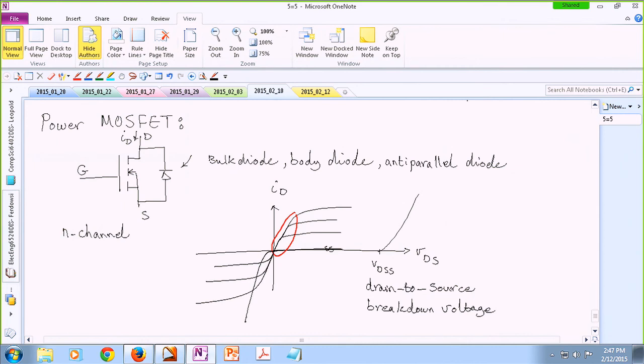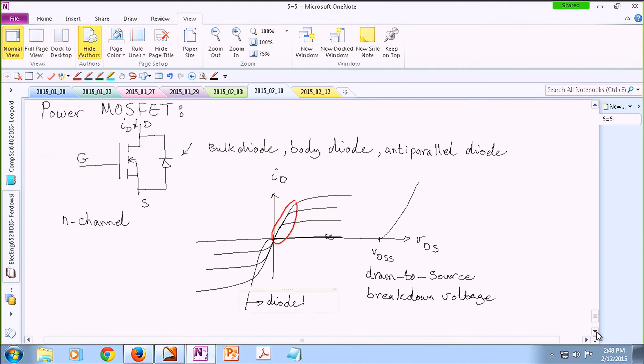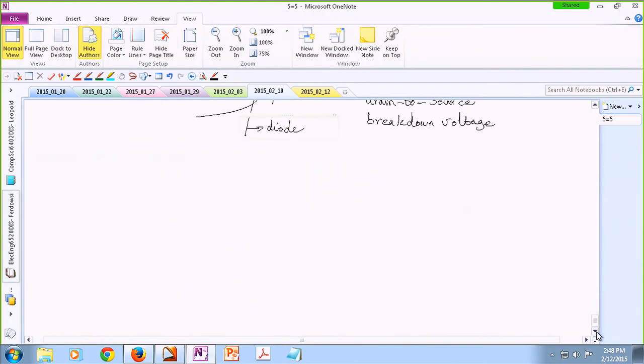The diode is also trying to conduct negative currents. So whoever wins is basically the one that exhibits lesser voltage. So this is for the diode. Okay. And most of the times the power MOSFET actually wins because it exhibits a smaller voltage across its components. All right, so if you want to idealize this device, you will get something like this.